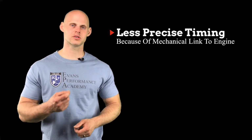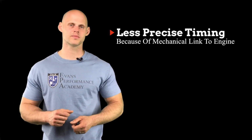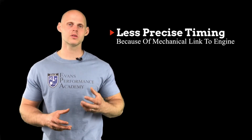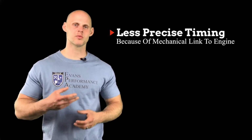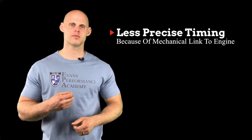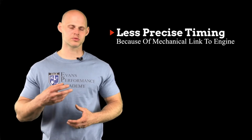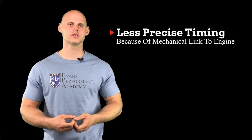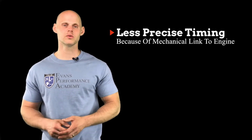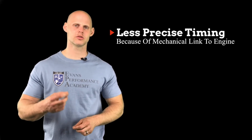Now, distributed spark ignition systems are inherently a little less precise when we compare them to the other ignition systems we're going to look at in a second. And this is because we have that mechanical aspect. So we're going to have that gear and the shaft and the rotor, and there might be a little bit of slop or play or misalignment, and that might transfer into a little less ignition precision. So if we say command 30 degrees out of our ECU, we might not see exactly 30 degrees, and we might see 29 or we might see 32. So there's going to be a touch less accuracy using a distributed spark system.